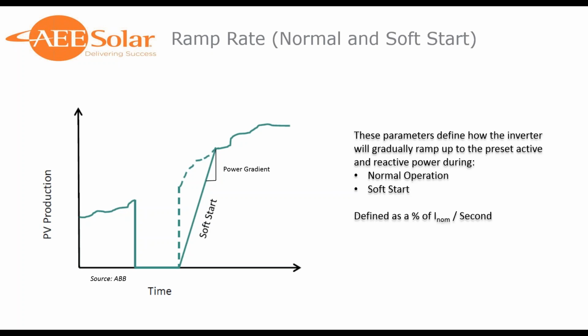That can be a really, pardon the pun, a really rude wake up for a grid to see an inverter, let's assume this is a 5 or 7 kilowatt system, drop offline, jump back online and requalify and continue working. In a scenario where you've got 2 or 3% PV penetration, 1 out of 100 homes, 1 out of 200 homes, the grid can absorb that.